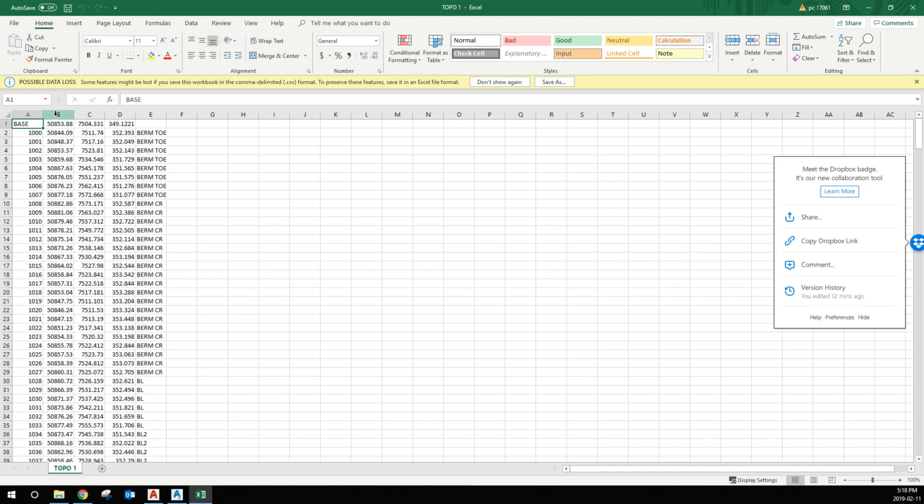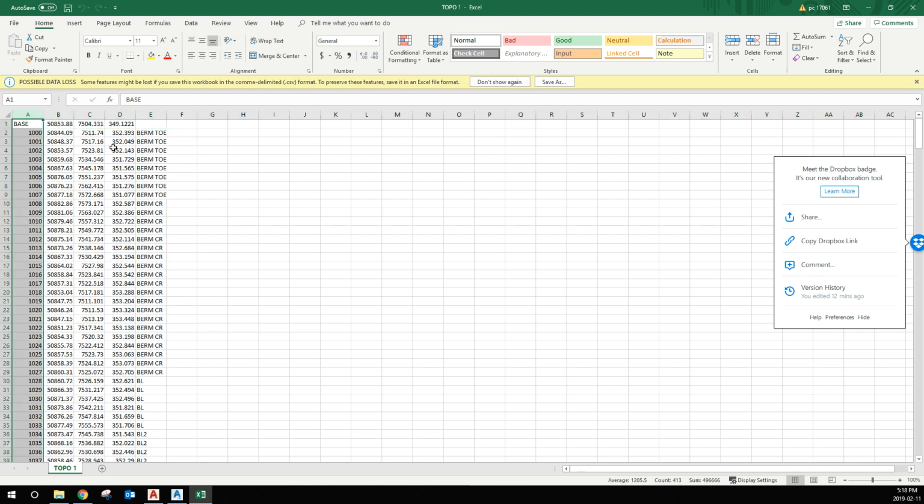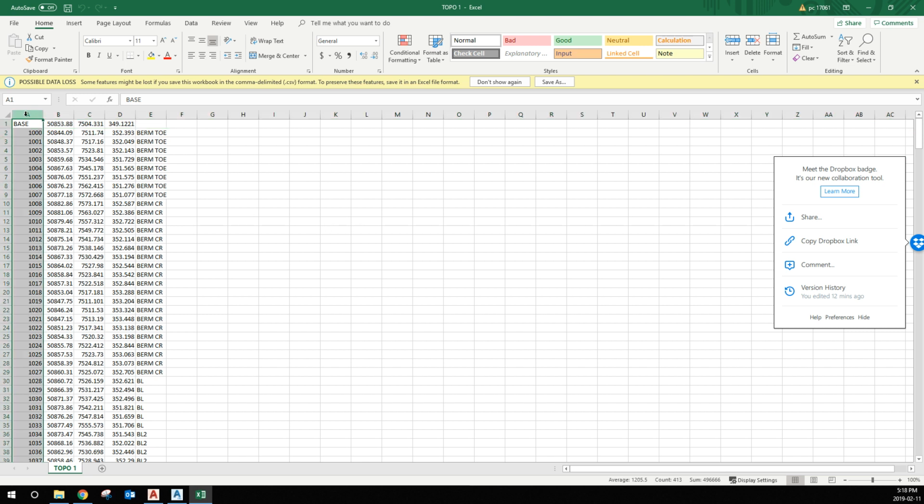Generally, when I get them up north here, you can get them in different formats. Sometimes you'll see an XYZ. Sometimes you'll see a point name here, but generally I've been working up here 10 years now and I've always gotten them the same way. So we're getting your point number, northing, easting, elevation, and description. So that's P, N, E, Z, D.